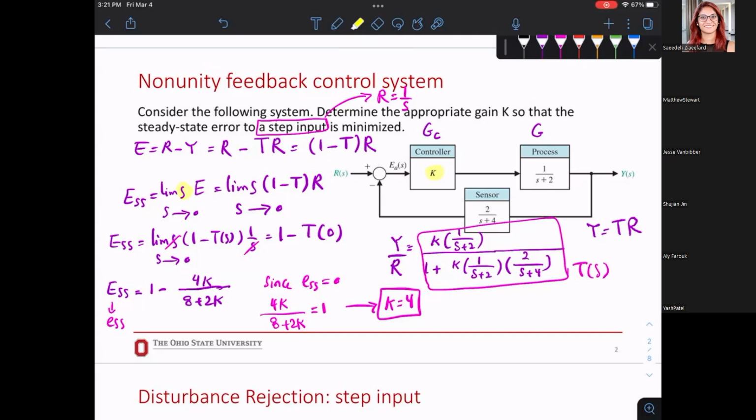What does your system look like, or could look like, if you only had one requirement and that's the steady state error to be 0? Yes. You could oscillate really violently for a really long time and then eventually get to it. Because this is at time equal to infinity, right? So it means that when the steady state error is 0, at time equal to infinity my system eventually will track my input. There will be no error. It exactly goes where I want.